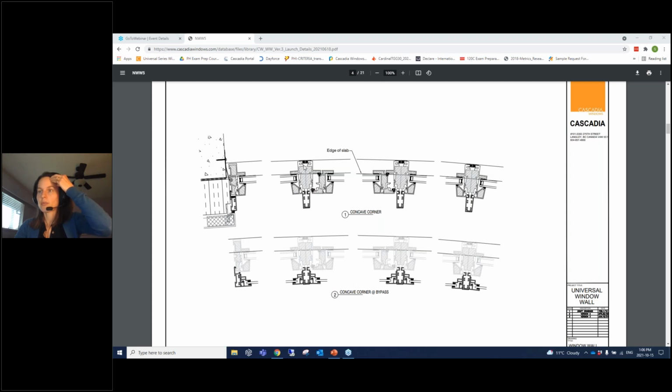So all of the portion in here is the Universal Series fiberglass with foam insulated window, and then you have a small aluminum piece here, and this is the window wall extension here. Those are outside of the thermal envelope. So this is inside your building, so same temperature, and then this is outside.